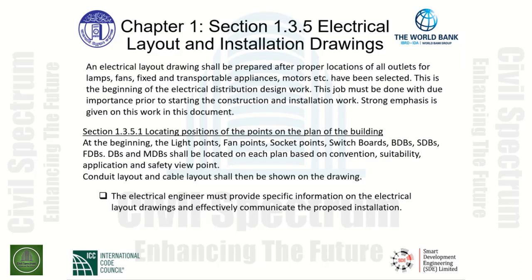1.3.5.1, locating positions of the points on the plan of the building. At the beginning, the light points, fan points, socket points, switchboards, BDBs, SDBs, FDBs, DBs, and MDBs shall be located on each plan based on convention, suitability, application, and safety viewpoint.